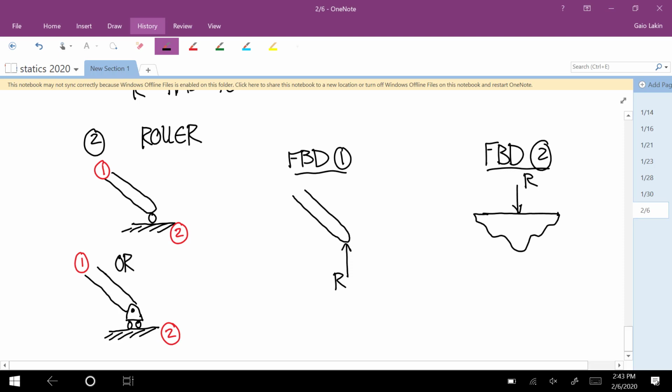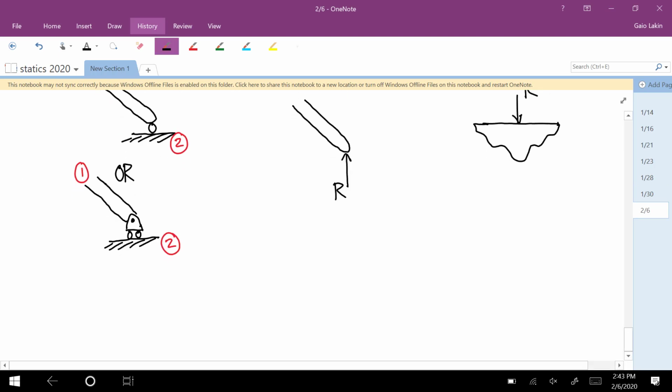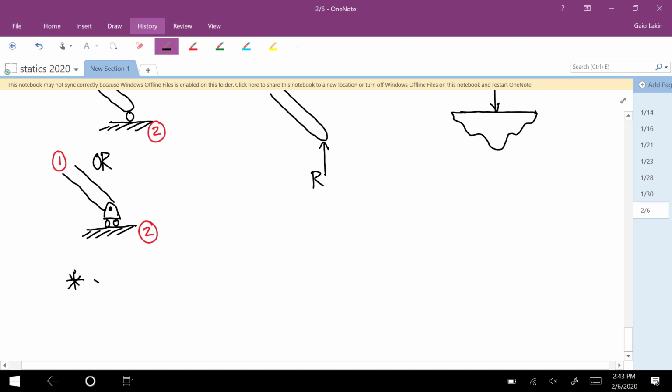Okay. That's right. So in 2 dimensions, couples, any kind of rotational thing can only be about the z-axis. Z or negative z, yep. What do you think about the sign of this r? Can it be either, or does it have to be positive? Yeah, it has to be positive because this can only push. So notice r has to be positive.